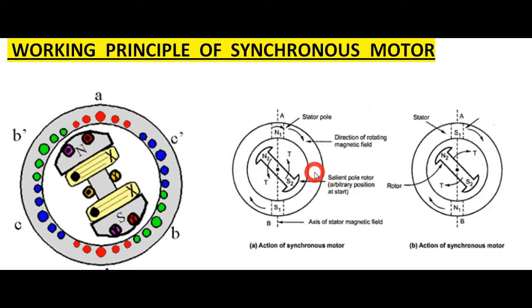In this position, see, here we come to the conclusion. During the first half cycle, the rotor just tilts in the anti-clockwise direction. During the next half cycle, the rotor moves in the clockwise direction with respect to the stator. See, with this continuous and rapid rotation of the stator poles, the rotor is subjected to a quickly reversing torque. Due to the inertia of the rotor, it will not respond to such torques and will remain stationary. Therefore, a synchronous motor is not a self-starting motor.